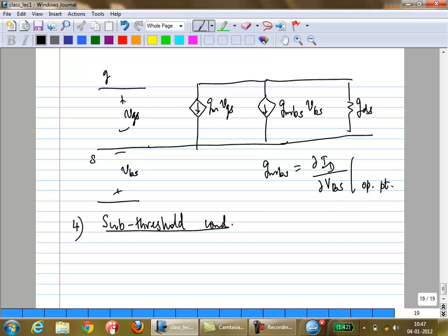The reason is you're assuming that the transistor gets inverted immediately. As you keep increasing the voltage, you assume that the inversion happens instantaneously. It's actually a gradual process. If you keep increasing voltage incrementally, the inversion region will slowly form. So instead, you'll have three regions: weak inversion, moderate inversion, and strong inversion. The subthreshold conduction usually refers to the weak inversion region, and there are some special characteristics about it, which we are going to look at now.